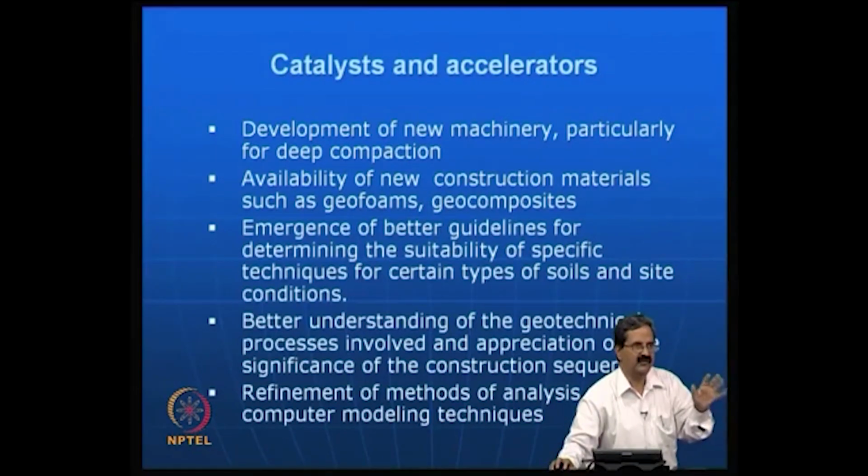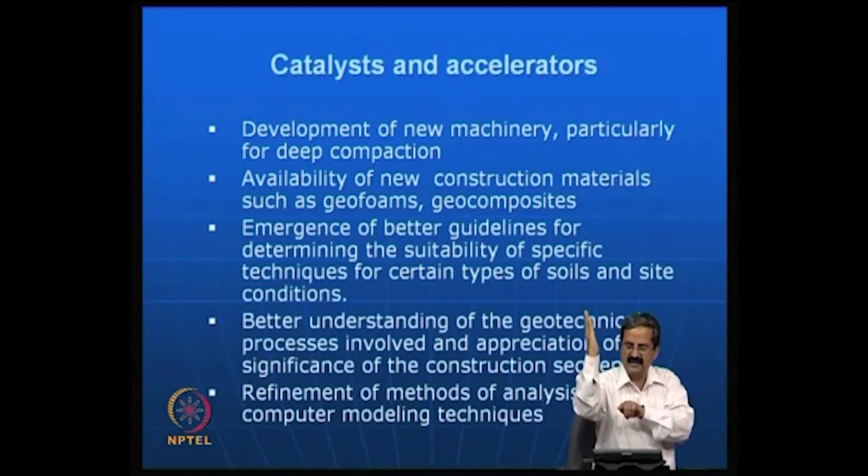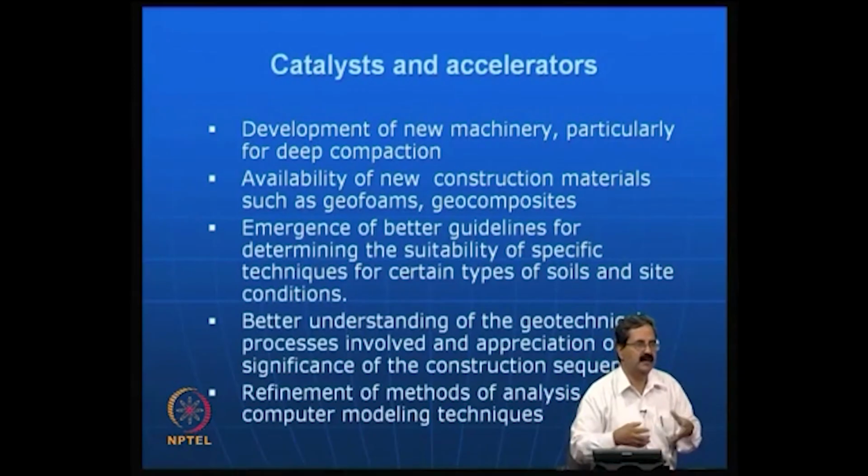C and phi and other engineering parameters will tell you some information, but if you want to really understand the deformation, like if there is a tall structure and I want to excavate here, I should excavate just 1 meter, then calculate factor of safety and deformation, then go for the next 1 meter, then calculate factor of safety and deformation, like that sequentially, put a reinforcement like this or put a sheet pile wall, many things could be done.